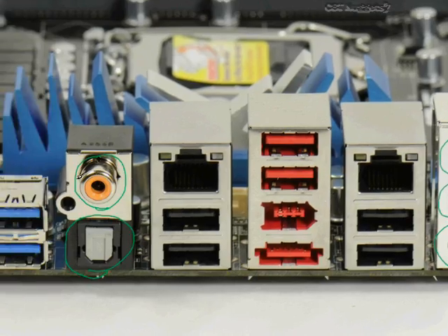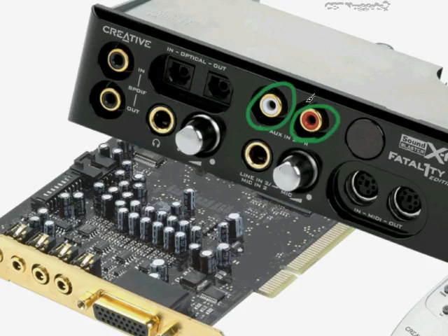Okay, you wouldn't want to plug any of those cables I just showed you into this, because the resistance is not the same in a coax cable. Even though the connector is the same, the resistance is not the same, and you're not going to get the results you want. So make sure that if you do plug something into that one, you use an actual coax cable. And then here we have some additional inputs and outputs.